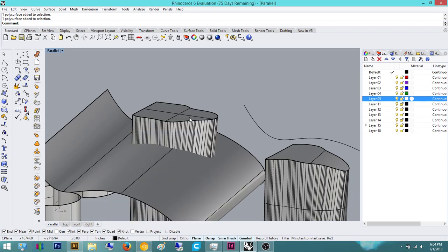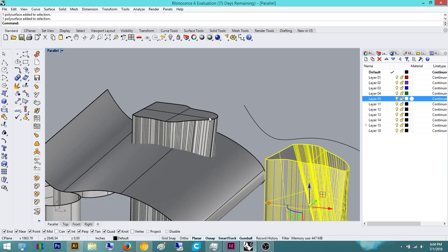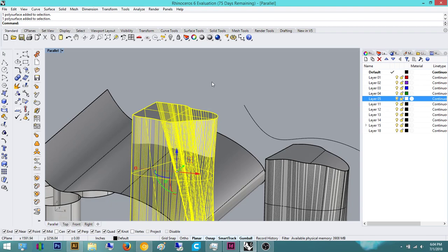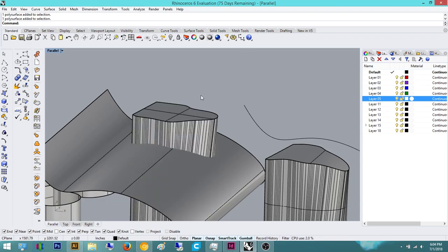This only works for objects that are completely solid, like this one, or this one, or this one, so be mindful of that. So we type in Boolean, and there's a bunch of Booleans, which I will go over in the next tutorial, because that will be transitioning from polysurfaces to carving and all these other things. And do split.